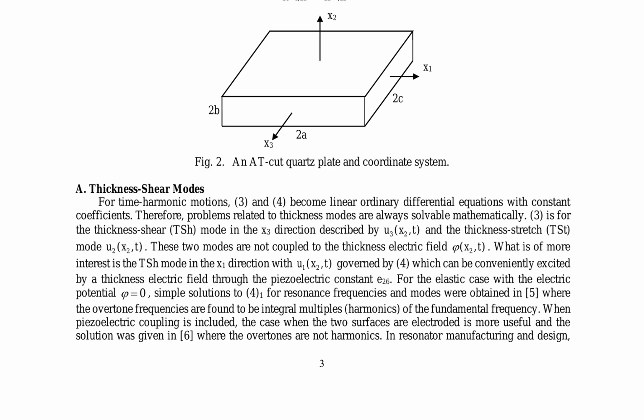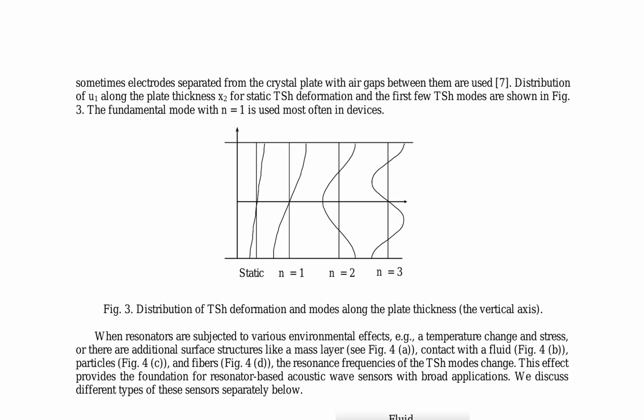The thickness shear mode in the x1 direction, governed by equation 4, can be conveniently excited by a thickness electric field through the piezoelectric constant e26. The distribution of the thickness shear deformation in modes along the plate thickness is shown in Fig. 3. The fundamental mode with n equals 1 is commonly used in devices.